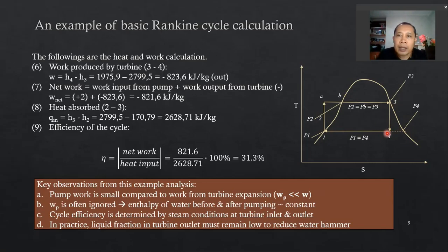And this is the reason why in reality the condition at 3 is almost always superheat. Okay, so inlet condition for real life steam turbine is almost always superheated, not saturated. That way, when you expand isentropically, you will end up with a drier outlet condition. Drier means it gets closer to this phase envelope here. Okay, going that way is wetter. Okay, going that way is drier.